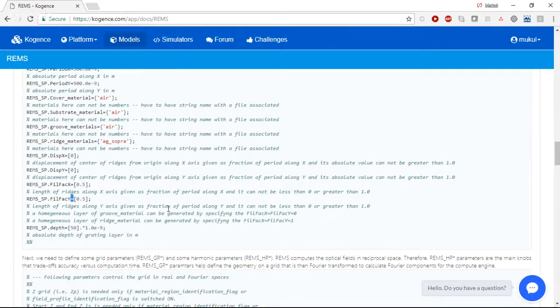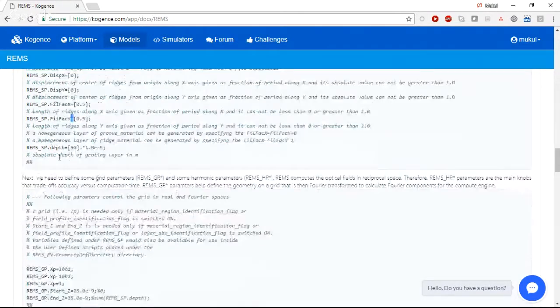So it's a two-dimensional photonic crystal with 50% periodicity. And what is the height of that layer? Note that in MATLAB syntax, these are all arrays. In this example, there is only one number, but you can stack multiple layers on top of each other, and this would just become an array. So you can put a comma and more numbers here.